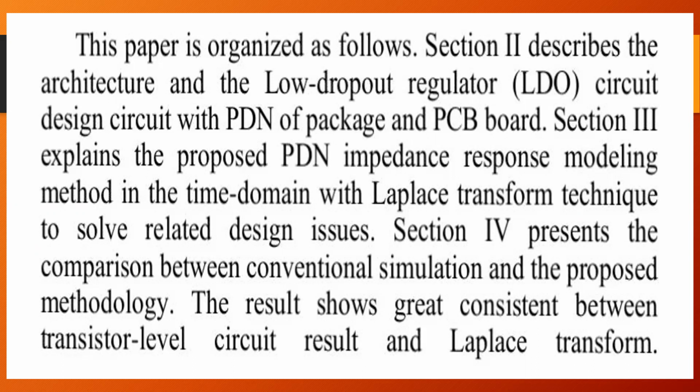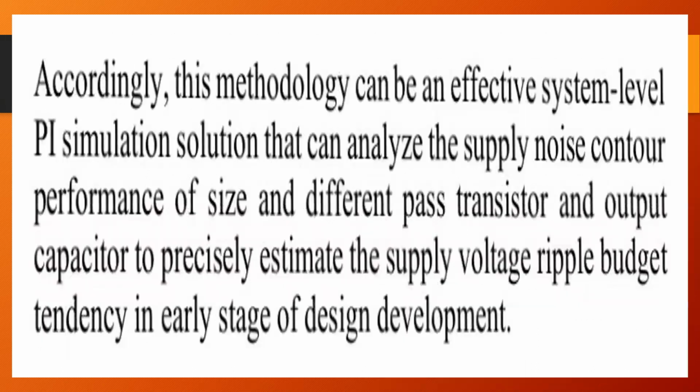The result shows great consistency between the transistor level circuit result and the Laplace transform. Accordingly, this methodology can be an effective system level PI simulation solution that can analyze the supply noise performance of different pass transistor sizes and output capacitors, to precisely estimate the supply voltage ripple budget tendency in the early stage of design development.